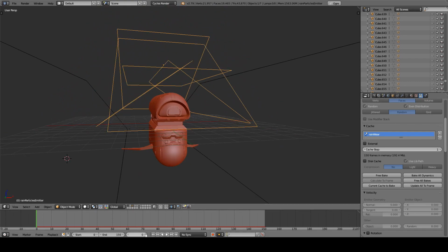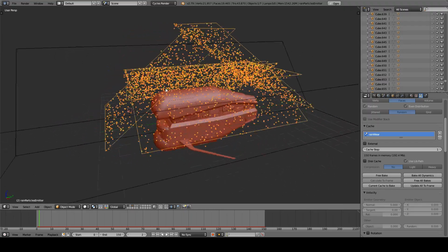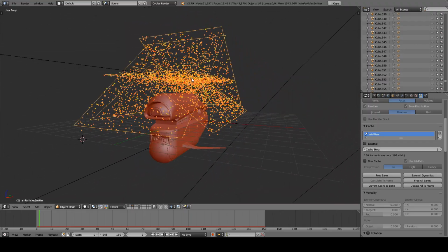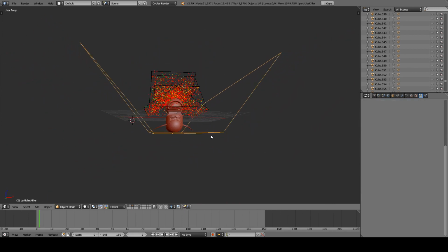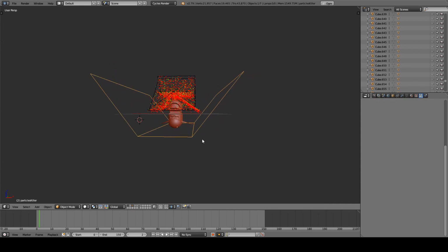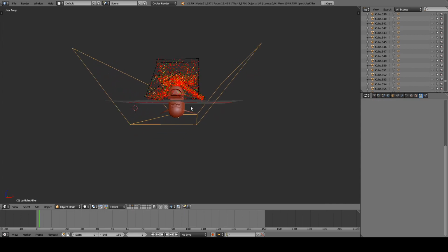Now that you have a clear view of what your model should look like, let's proceed to generate this rain mask. The first thing to do before baking is the rain particles simulation itself. I placed several particle emitter planes to make sure that every part of the model would be exposed the way they would be exposed to rain. At the bottom, this shape is here to kill particles that we are sure will not contribute anymore. This helps reducing simulation time.